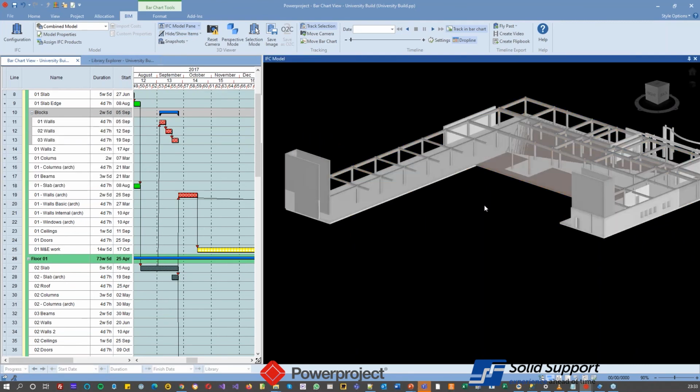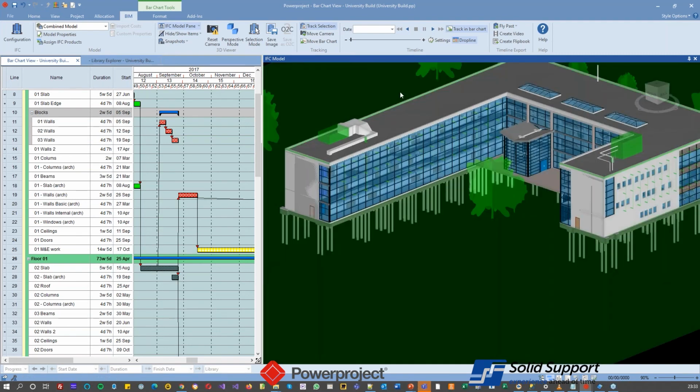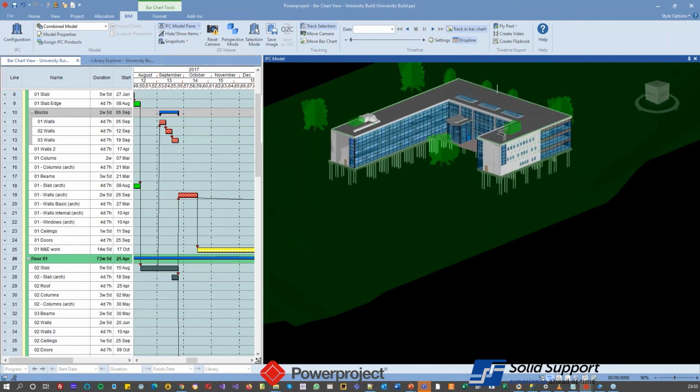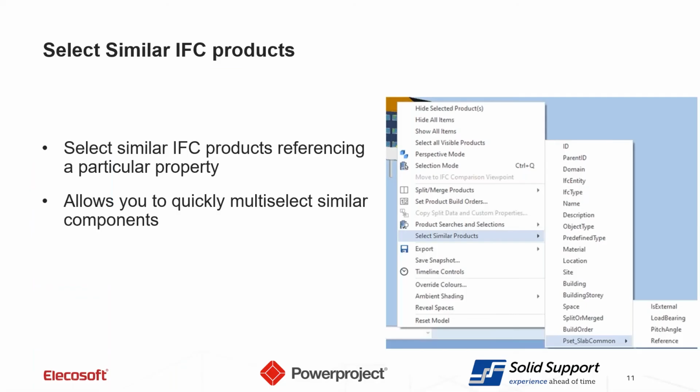And again, just to show you here, if I select all of those objects there, once they're all selected, I can say in there that I only want to show any selected tasks. So now that is showing me just that part that I've highlighted. That could particularly be one particular trade's items in there. If I just did that, those items there, I could then go again and say show any selected. So that's maybe one particular trade, and I may want to run a simulation just for that. So it becomes a really powerful way to add to that. Again, at any point, just go back to show all items inside there.